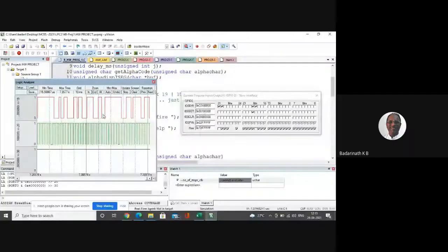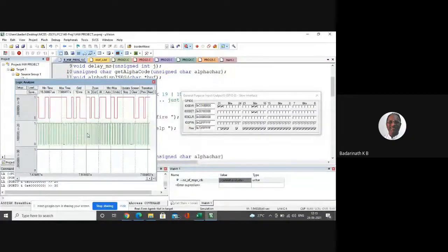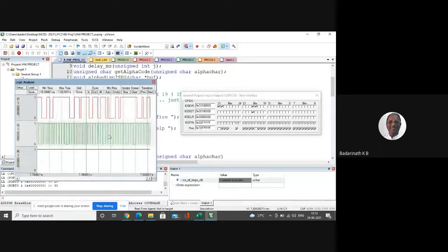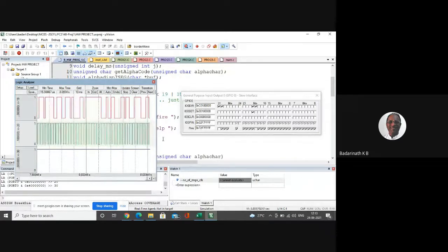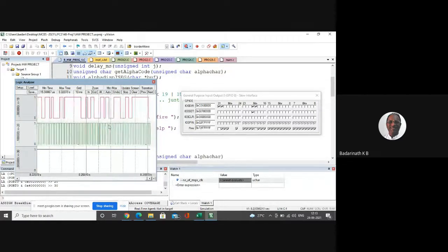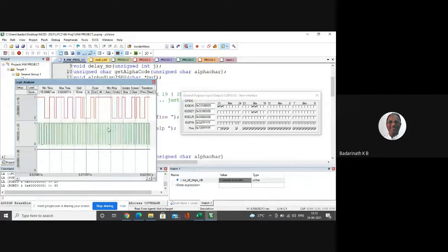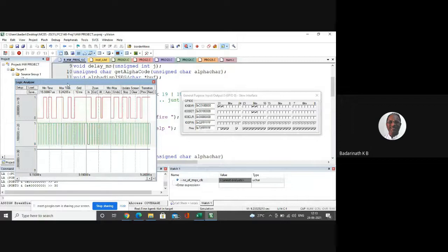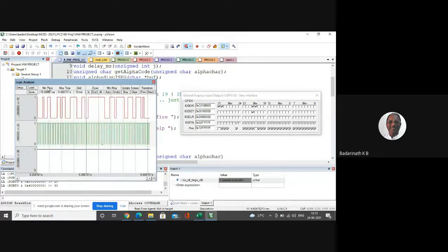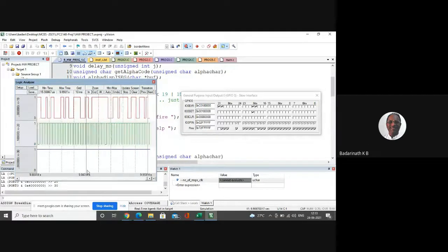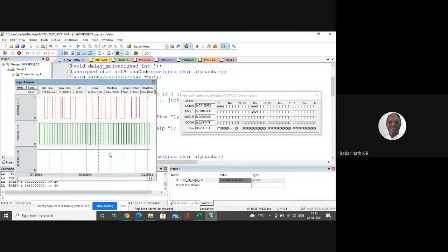You can see that this is the 7-segment program, where this is a device driver program. Whenever you use a device driver program and implement it in hardware, a lot of issues will come. It will not work the first time. Then you have to use a logic analyzer. How do you use a logic analyzer? We have a logic analyzer in our laboratory. A logic analyzer is equipment where you use the probes and connect to the bits you want to observe on the board.